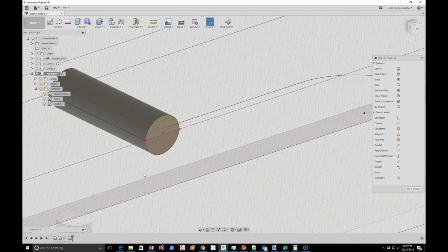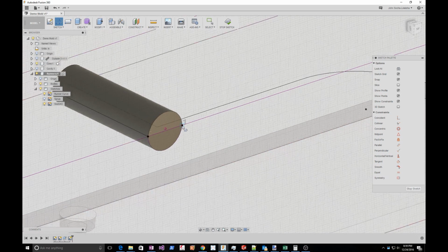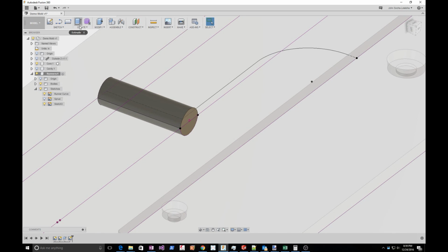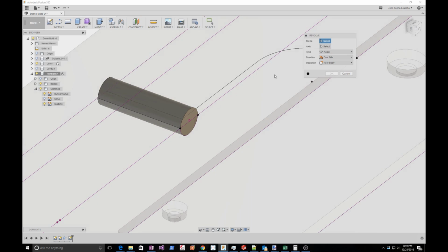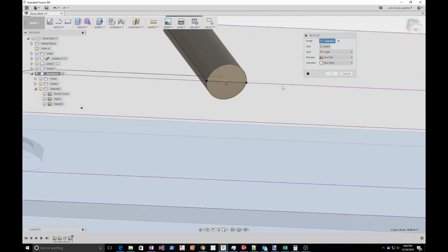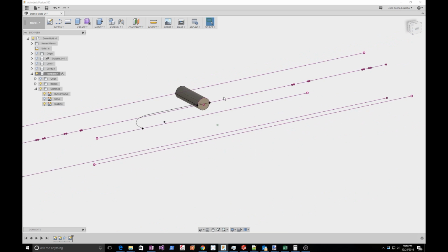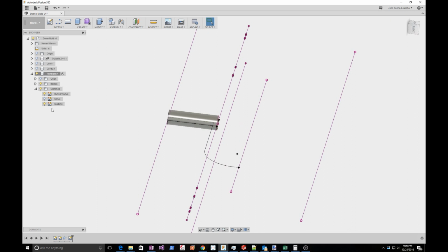And then I need to close it so that I can rotate this around. So I'll add a line here. Okay, stop sketch. And if I've done that correctly, now I can go in here and say revolve. Select this profile. Okay, that's not doing what I expected. So let's see if we can figure out what's going on. Let's hide the body here. All right, so it's pretty clear that I ended up projecting a lot more than I expected to.